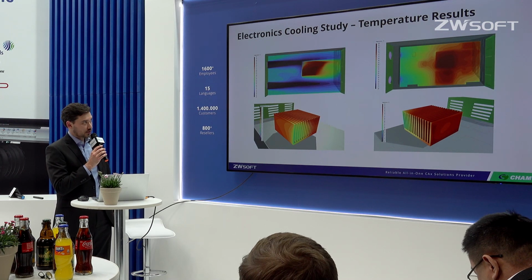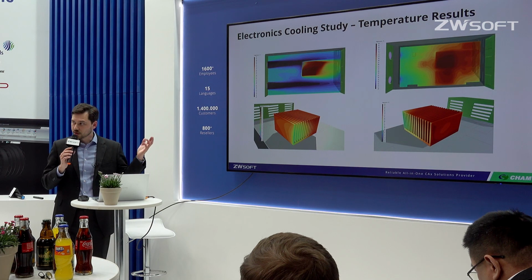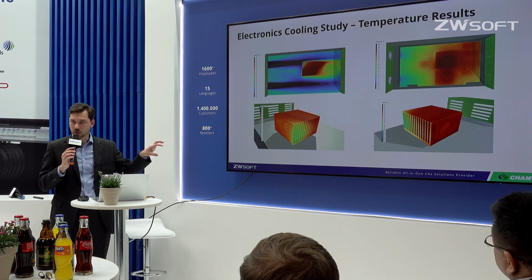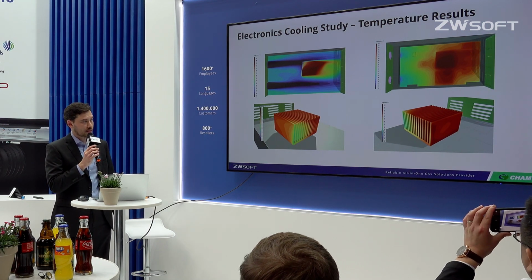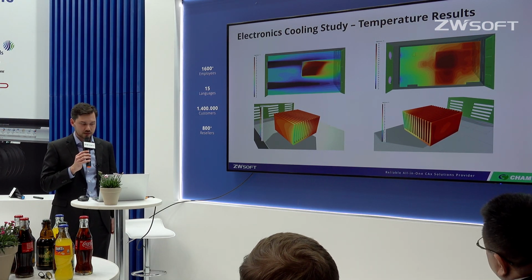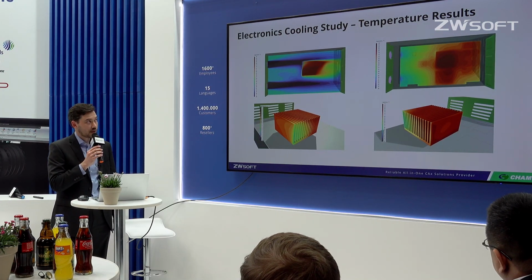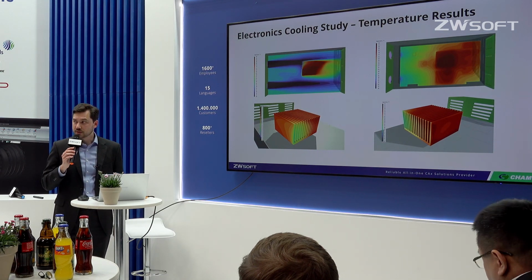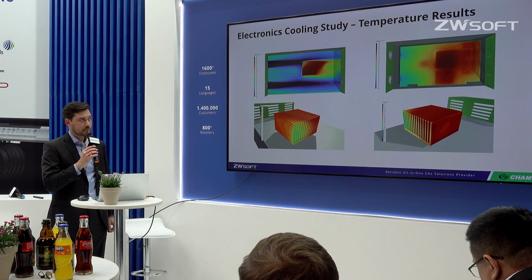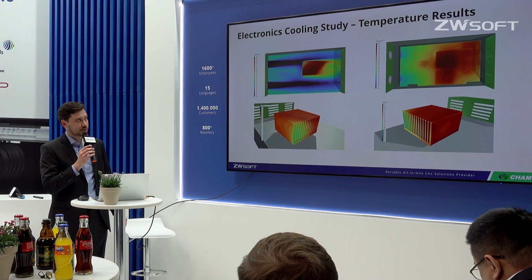We can also see that there's a relatively hot region behind the heatsink. So if you remember the velocity plot from just now, there was a hole or a close to zero velocity region behind the heatsink, and in there the heat is building up. So this is undesirable when designing an electronics case. The plot on the right shows the surface temperature of the PCB. So we can see that the chip is getting very hot. The actual maximum temperature inside the simulation, the 94 from just now, is inside the chip.